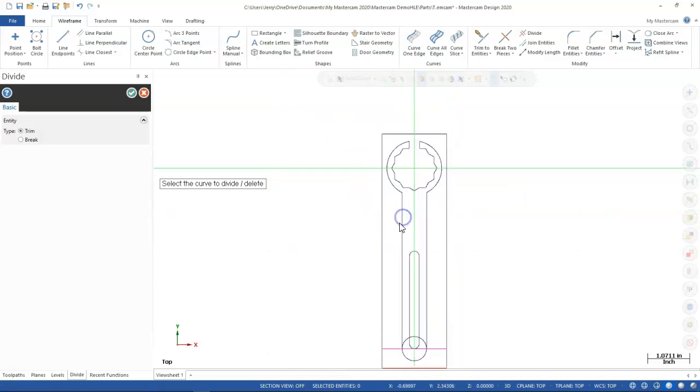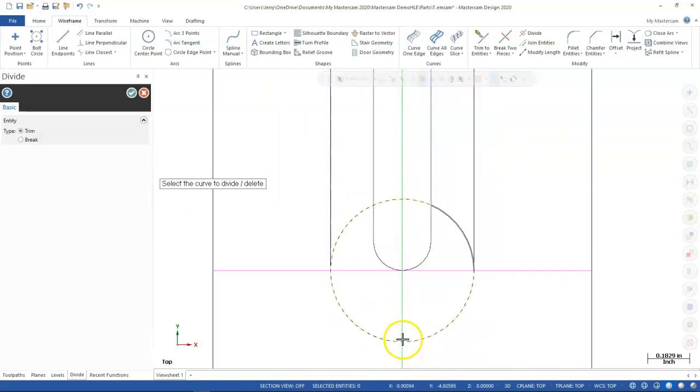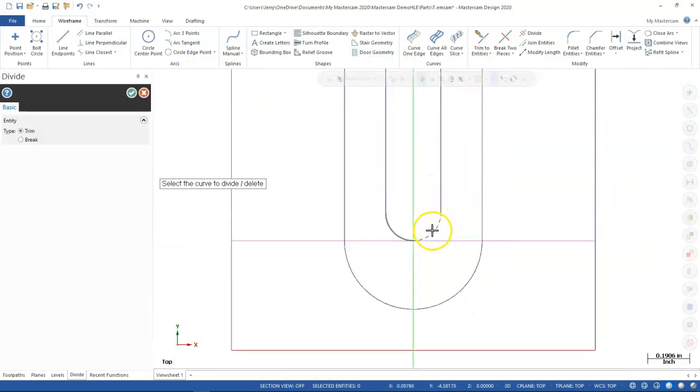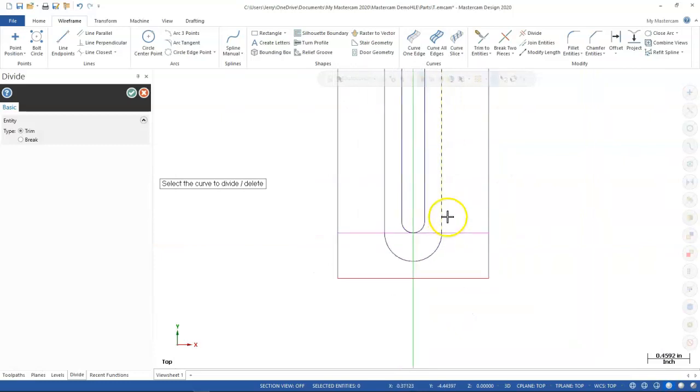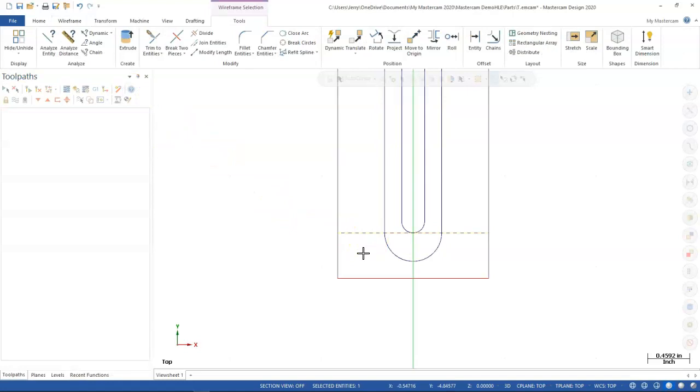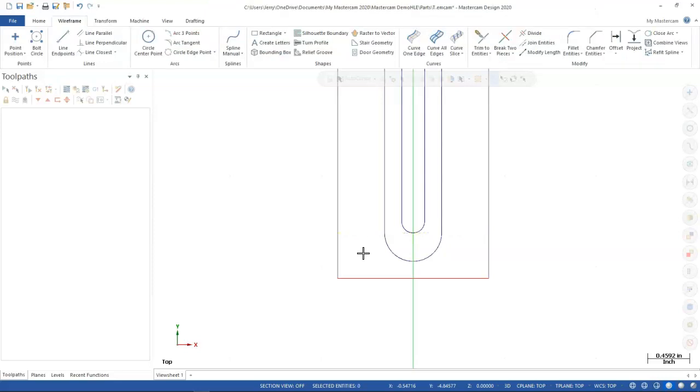All right, same thing down here. Let's right click and fit. And I'll zoom up a little bit. We're still in divide. So as I pick that geometry, then we can make that go away. And the construction line, since I'm through with it, if I thought I would need it again, I could put it on a separate layer and just hide it from the display. I'm just going to go ahead and hit delete on the keyboard with it selected, and then it goes away.